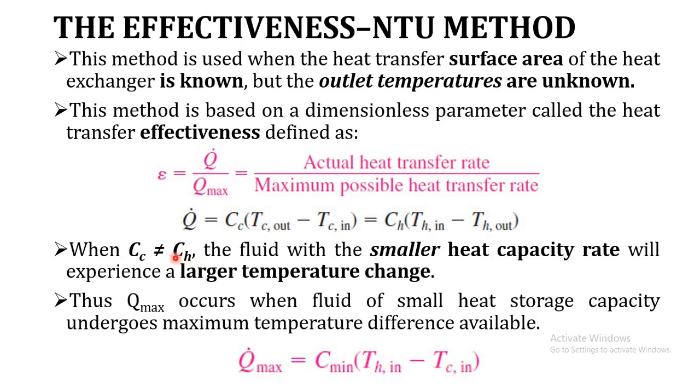Now, if Cc is not equal to Ch, the fluid with the smaller heat capacity rate, Cc or Ch, will experience the larger temperature change.